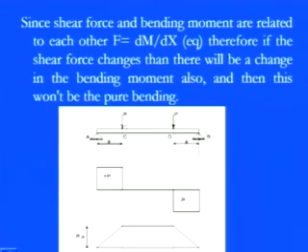So, when we are talking about those things, this is a pretty simple diagram in which two point loads are there, both going in the downward direction, and the reactions are coming in the upward direction. If you go for the shear force diagram, you will find that on the left hand portion we have the positive shear force, and this is the negative shear force, but there is no load application in between. So, there is no resultant shear force existing in between